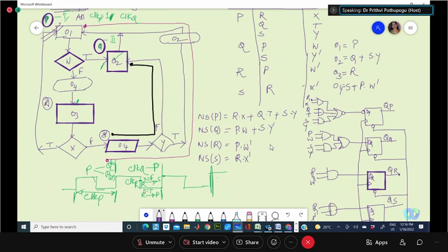Do you still remember the mixed logic, or have you forgotten? Logical true. Remember? Yes, ma'am. Okay. So whenever we are trying to tie one of the outputs to another input, logically both the levels have to be true. Levels, in the sense, the truthness has to be mapped. That is what we call compatibility of the levels.